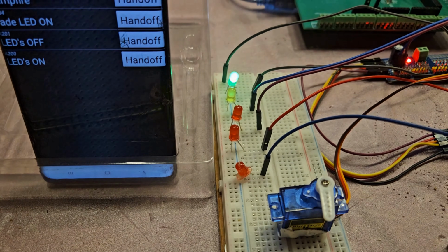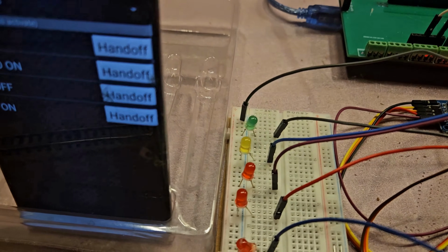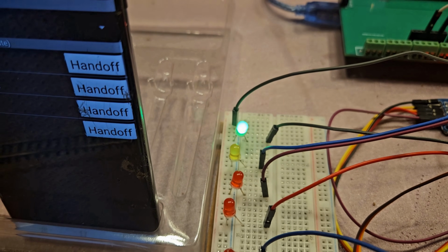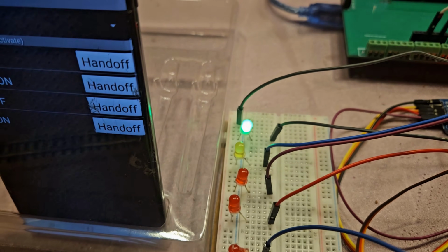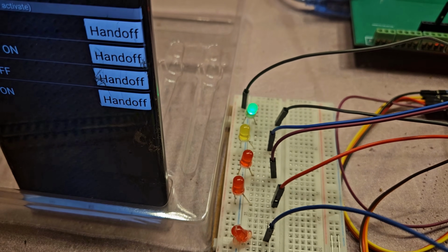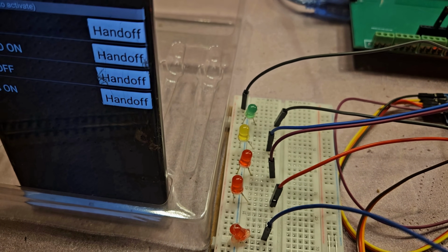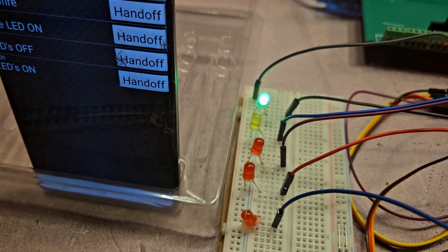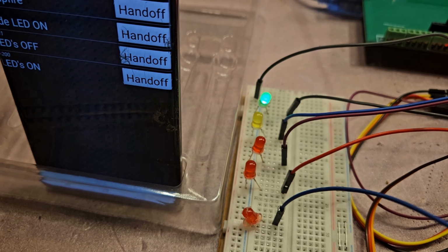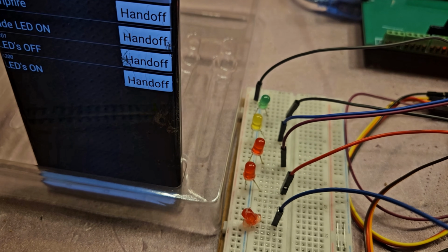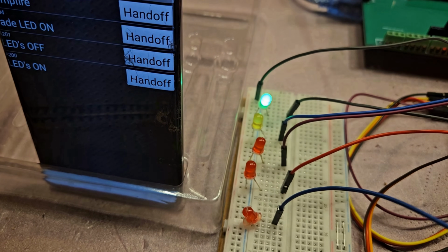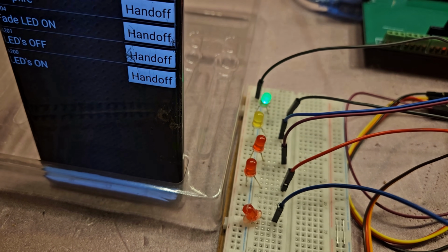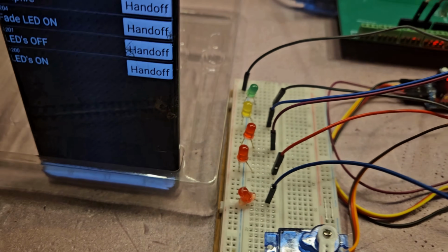Now we do the fade. I realize there's flickering on that as it fades in and out. That has to do with the frame rate of the video and the refresh rate on the LED. To the naked eye, it is not flickering like that. It's a nice smooth fade in and out from off to its brightness level. And then it fades down to 0 slowly, and then it should fade back up to brightness and then fade back down. Again, I apologize for the flickering in the video, but it just has to do with the frame rate on the video showing it up.